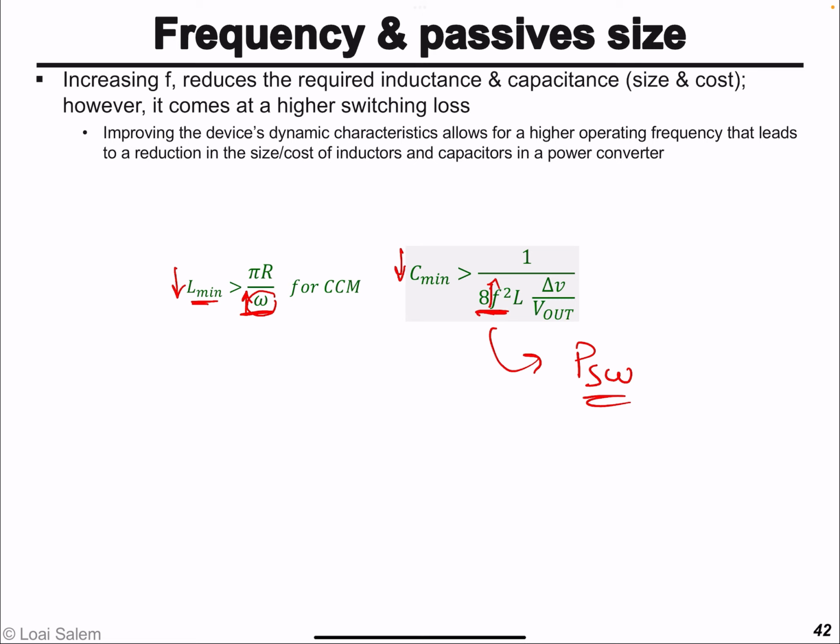And that's why the ability to develop power converters of smaller volume size, smaller magnetics, smaller capacitor sizes is basically by having better switches, better FETs that essentially can switch at very high speeds and cause lower switching losses. And that's how we move from silicon MOSFETs to gallium nitride and so on.